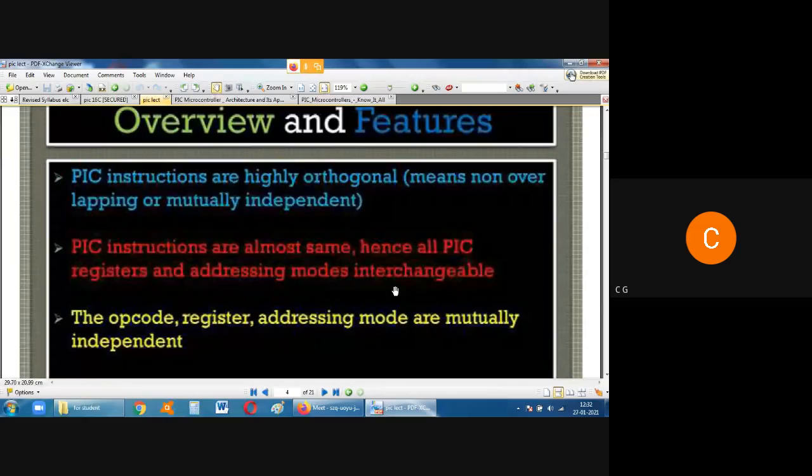Even if you want to store the data into memory, in the microprocessor, you have to load the HL pair and then store the content from that to register A, and then you do the mathematical operation. Once the result is available, you have to transfer it to register A, and then send it to the different memory locations.